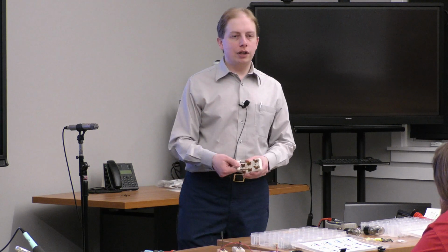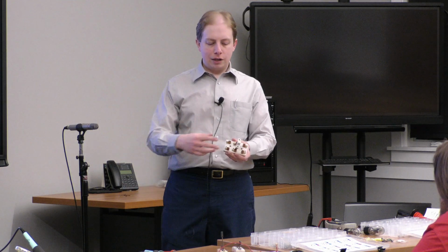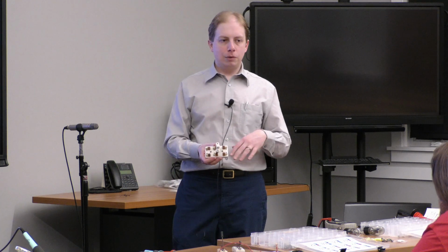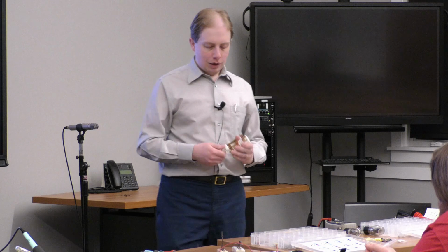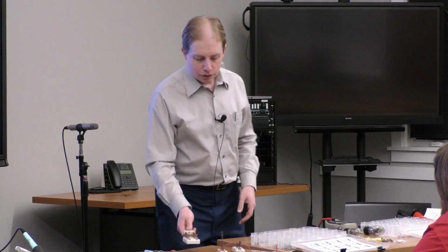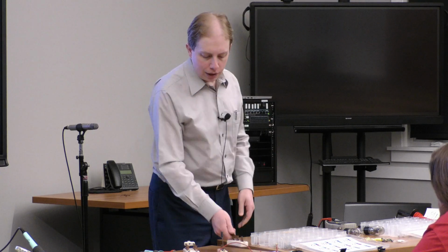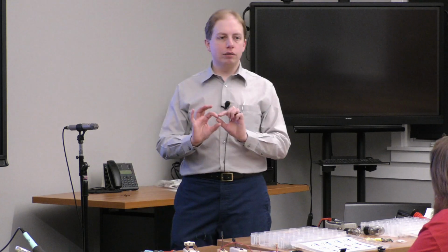There are always different practical applications. Maybe this is an antenna switch. You've got two different antennas. You connect your radio to the middle terminals, and you connect two leads off to this antenna and two leads off to this antenna, and depending on which one you want to use, you can just switch back and forth. Or Michael's got a case where he's got two different power sources for his shack, so he can switch it one way for utility power and another way for solar power. Real common. But it's common to have these switches packaged into very small devices and used inside a radio.